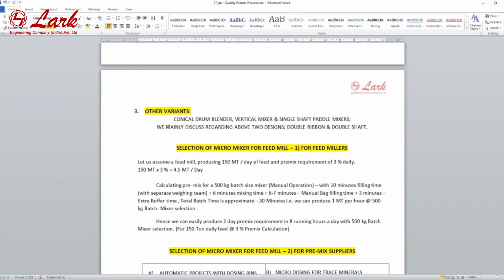Instead, put in one VFD costing 60,000-70,000 rupees, and then for every starter and pre-starter just change the RPM speed, and you can have different particle sizes from the same feed mill with the same VFD.